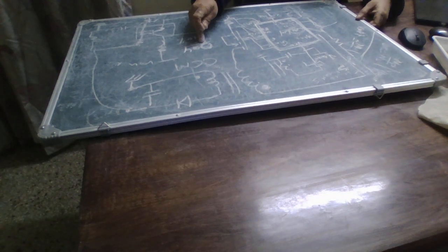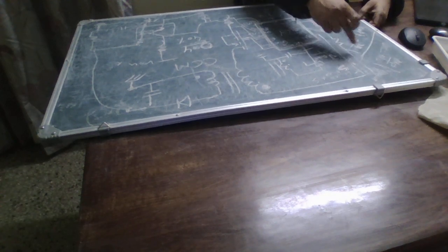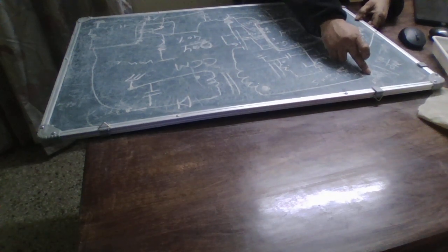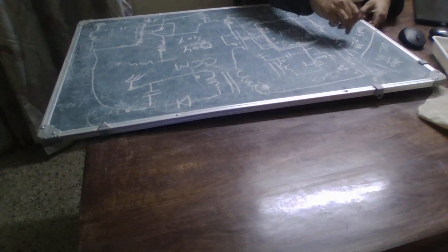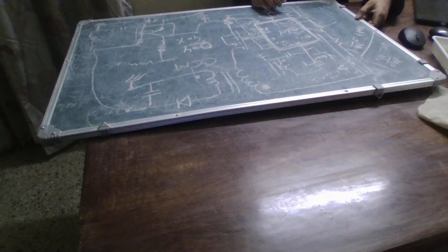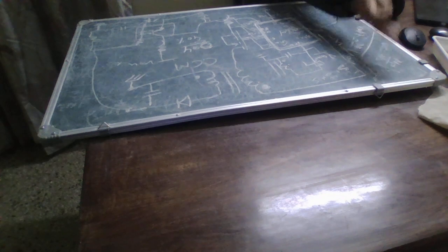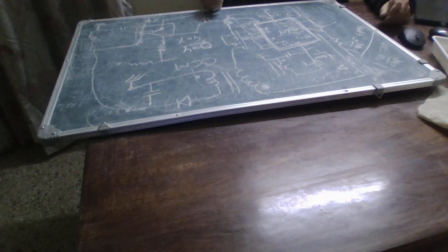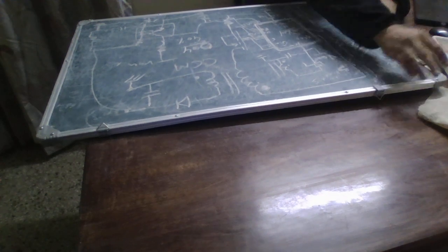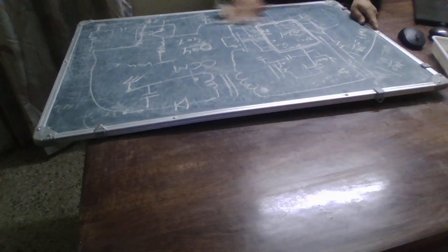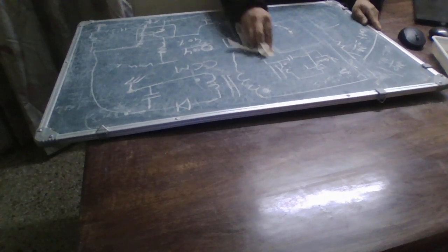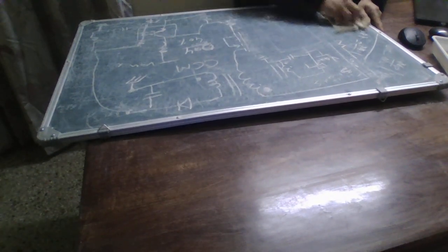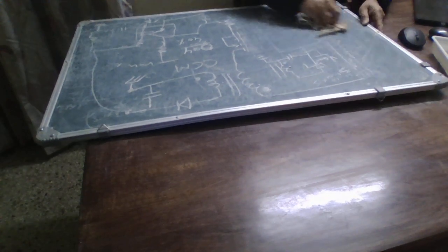Putting 0.4 here, we know the V load voltage is 5 volts, and we know the supply voltage, which I have mentioned as 18 to 36 volts, so 18 we are going to put here. Now I need space to write, so I remove this IC, because the next circuit can be more easily explained now.